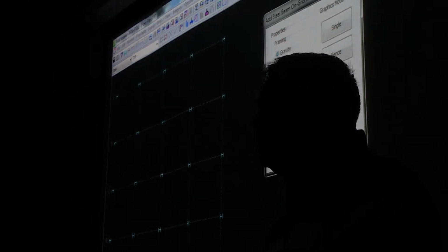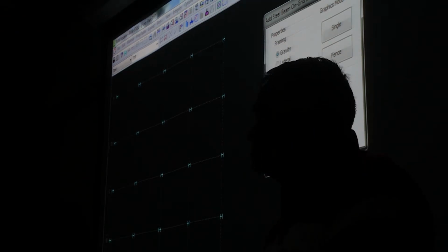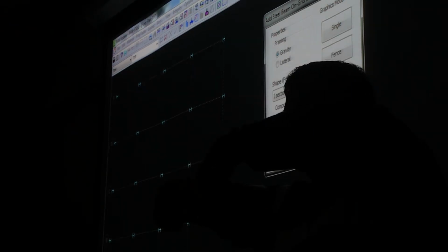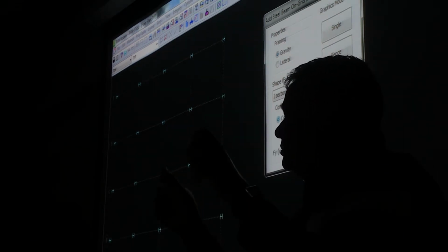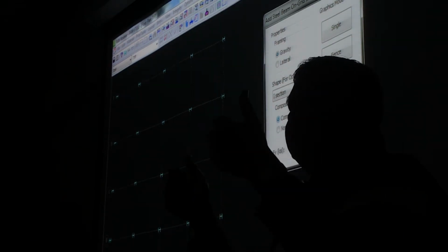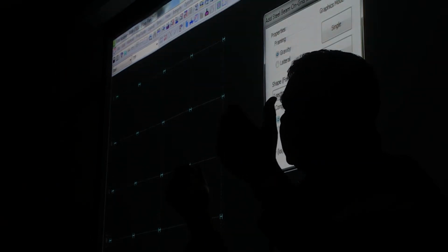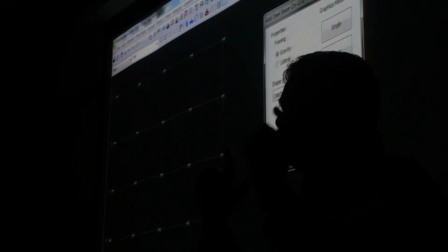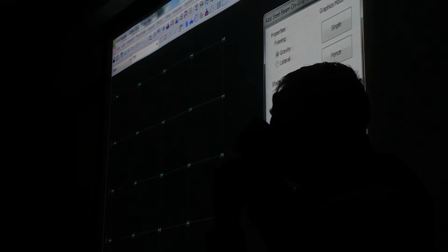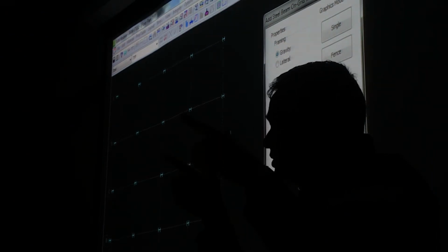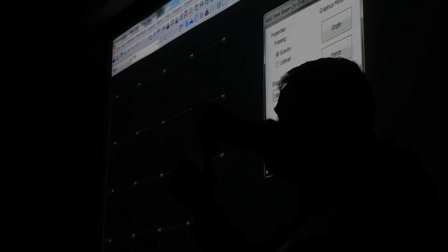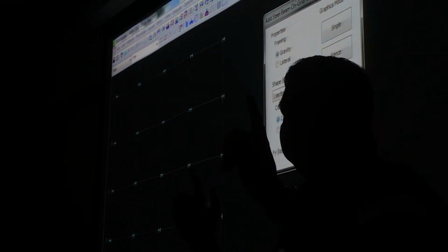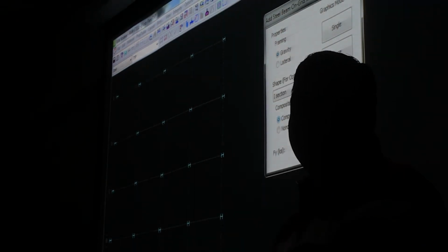The only thing is, the beam has to be in positive bending. That means compression should be in the top. If it has a negative bending, tension in the top, concrete cannot take any tension, so it will not work. So composite action only works for positive bending. Where is the positive bending? When there is a gravity load and the beams are simply supported. That's when you have positive bending.